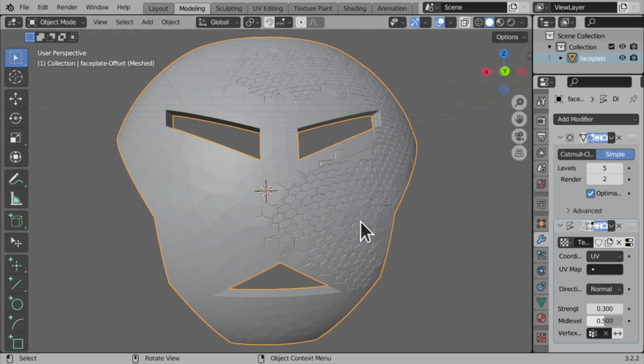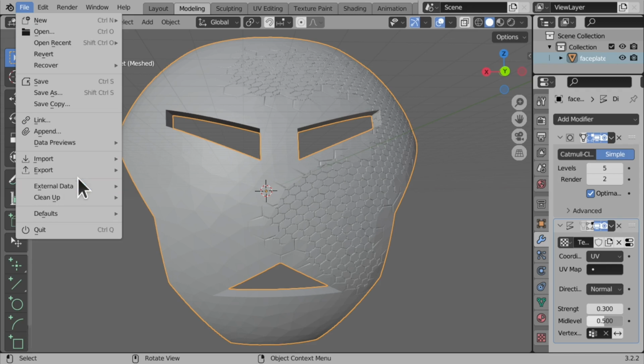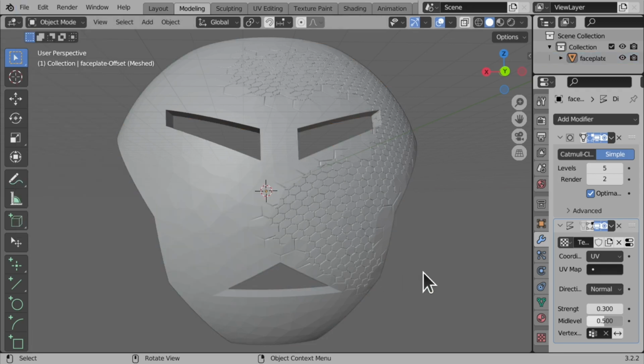Hope you found those two tutorials useful. We're mixing open source software there, FreeCAD as a parametric modeler, and Blender to do some finishing, ready to send that over to a 3D printer. And remember, we can just file, export as whatever form we want, STL, etc. And we can chuck that over to our 3D printer ready to print. So I hope you found that two-parter useful, and I hope to see you again soon.